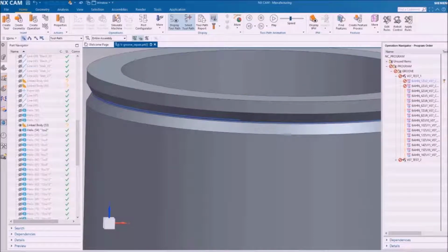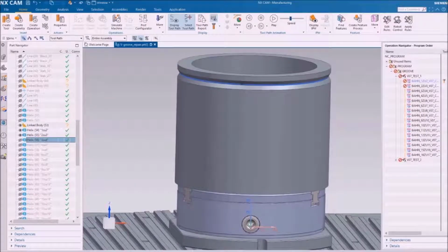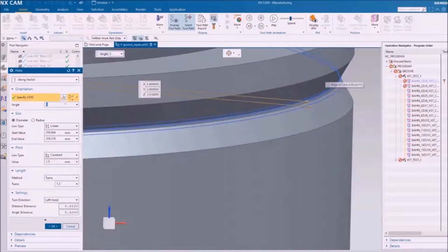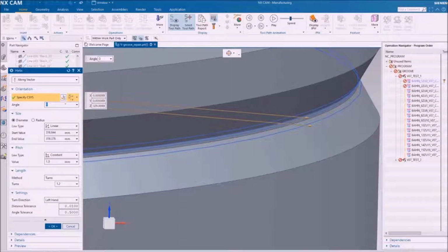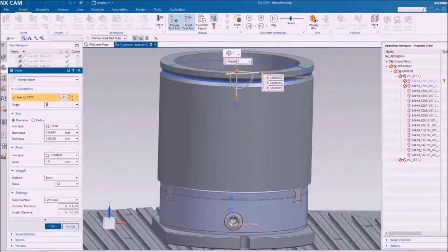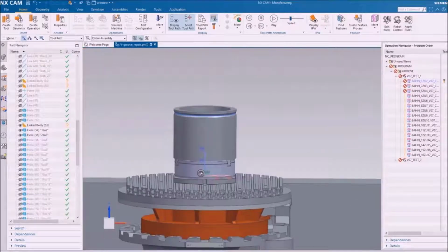The first winding is in upward direction. 2 windings in downward direction follow. Then 3 windings in upward direction, and so on. Following this pattern, additional windings are iteratively programmed until the tool traverses the groove completely from the top to the bottom.